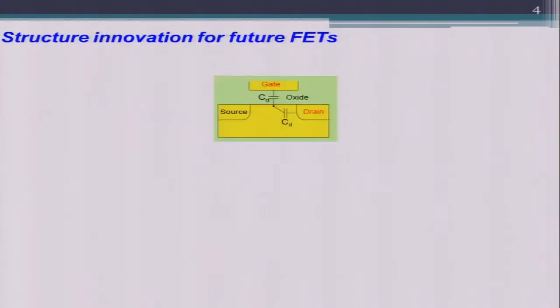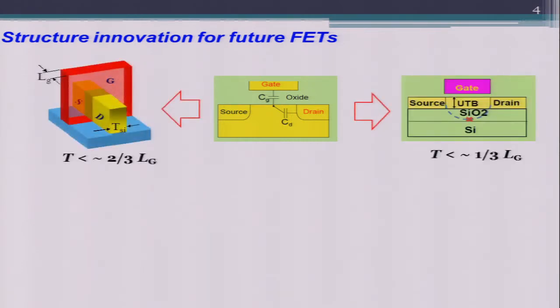So when we are designing our next generation transistor, not only do we have to think about the tunneling and controlling the tunneling probability, but we also have to think about the electrostatic issue. The electrostatic issue will govern all future transistors, regardless of whether they're MOSFETs or tunnel transistors. And in this regard, there have been really 2 approaches taken to reduce the short channel effect, both either fully or partly proposed and demonstrated here at Berkeley. One is the ultra-thin body SOI, and the other one is the FinFET.